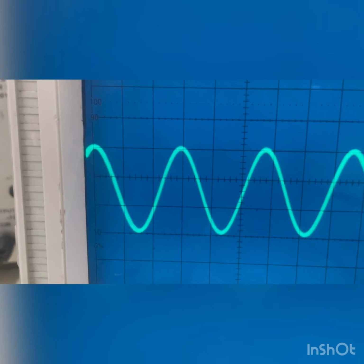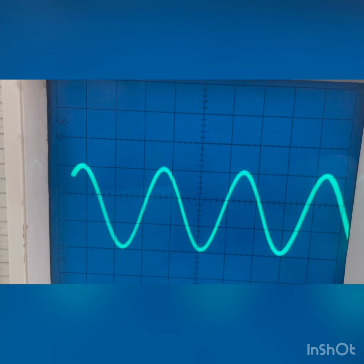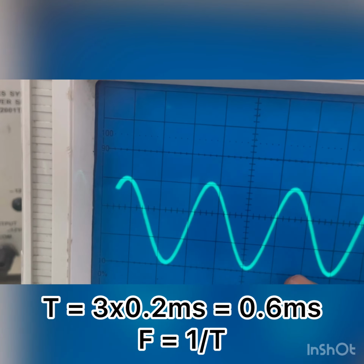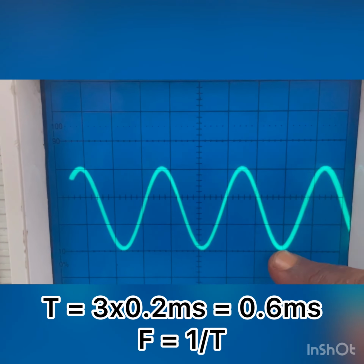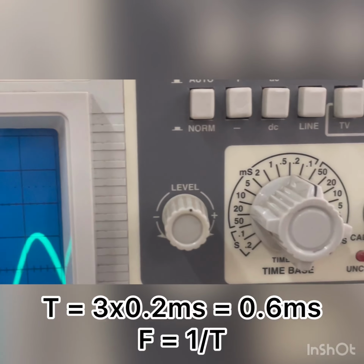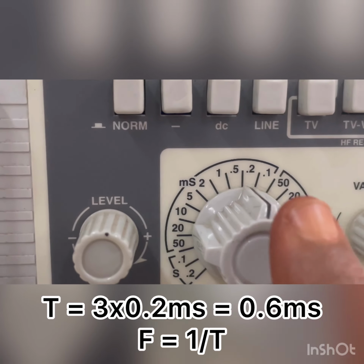For that, we measure square boxes in the horizontal direction for one cycle. So, 3 boxes in the horizontal direction multiplied by 0.2 millisecond time per division gives us a 0.6 millisecond time period, and 1 upon T gives us the frequency.